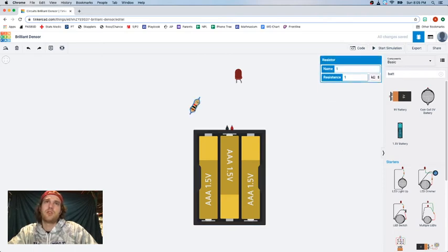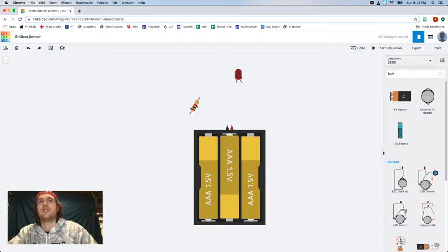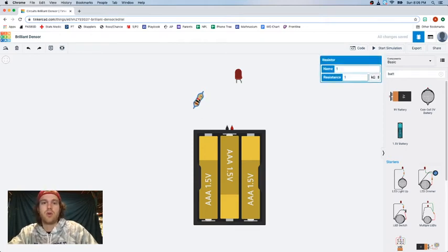So here's my resistor. My resistor is reading brown, black, red, which is 1, 0, so 10 times 10 to the second, which is 1,000 ohms, or 1 kilo. There we go. So we can use this, and the stripes on this program will follow what we just learned.